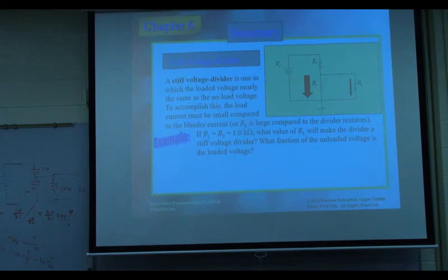So what you do is you want to make this system stiff. Means your input impedance, your output impedance of your equipment, meter, or anything, to be as large as possible. So for the system you want to measure, looking into your equipment, it will be almost an open circuit. The resistance is very large, and does not affect the system.